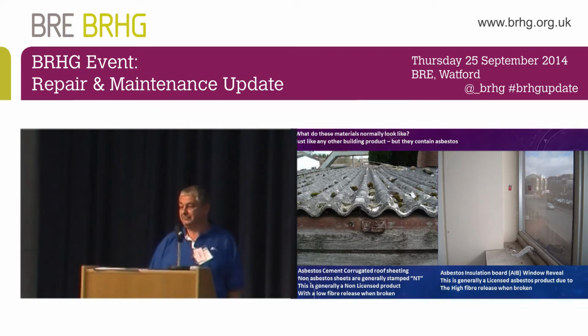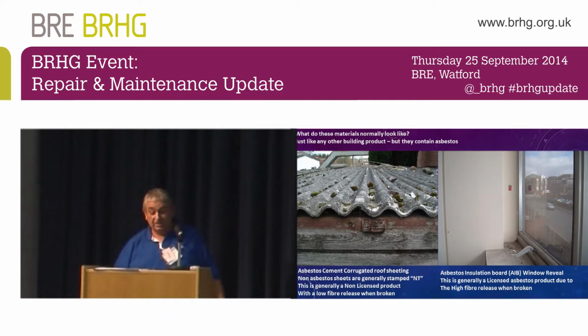End of problem. And they also had too many guys in the area picking up asbestos debris. I said, why are you doing that? We've got excavators on site and we've got closed skips. I need one man. That's the only man at risk. I don't need five guys picking. So we had excavators. They just hadn't thought the job out properly at all.